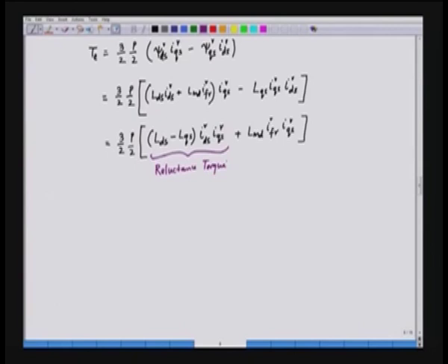Because it is present due to the reluctance variation in the d axis and q axis. And what about the next part? This next part is called the field torque. This is present because of the field winding equivalent current, that is I f r. I f r is the equivalent current of the field winding because of the permanent magnet. So, this is the equation for the torque.